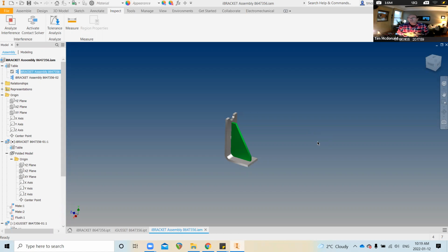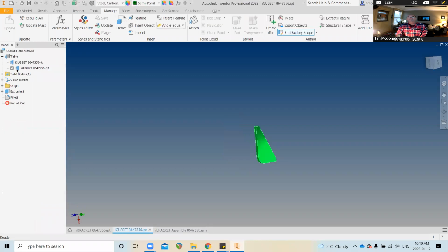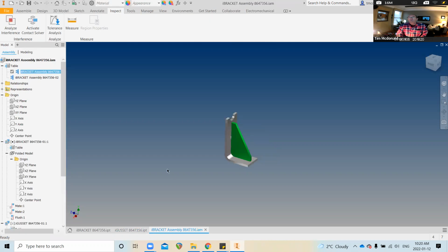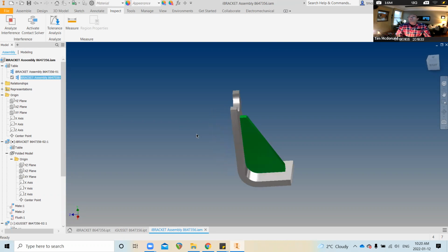We've gotten to the point now where we've created 2 components, created iParts of each of those components to have 2 configurations basically, and they show up under the table in our model browser over here for the specific components. And under the assembly, we've also created an iAssembly where we can substitute different components in and have representations for those assemblies thusly.